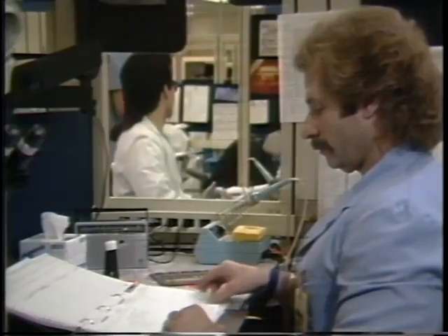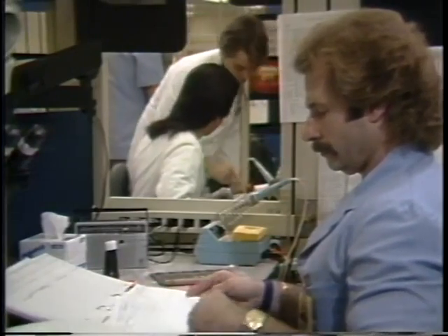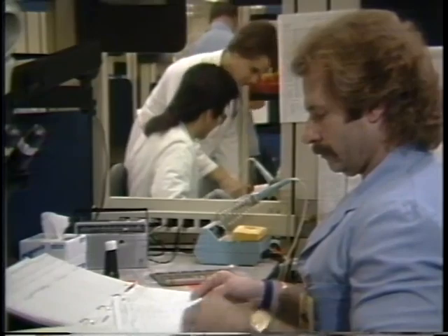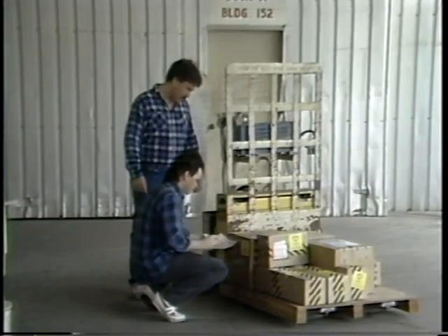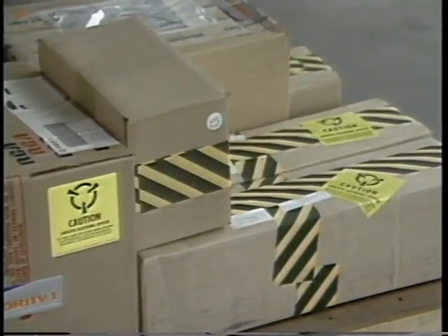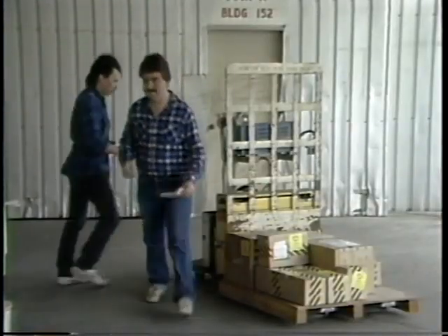An important rule to remember when working with ESD-sensitive components is always let your leader or supervisor know if any ESD-sensitive device has been mishandled or unprotected. Allowing a part to be shipped without being retested will cost more in the long run. A single damaged component can cause serious system failures and in some instances may take a life if it fails at the wrong moment. ESD can be controlled, but everyone must share the responsibility. The cost of damage resulting from ESD over a period of time can't be determined, but the rework and retest on a missile electronic package would cost a minimum of $15,000.